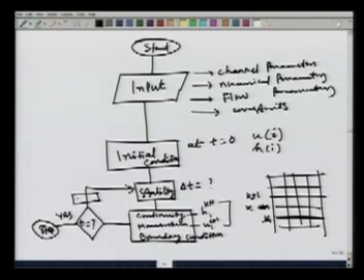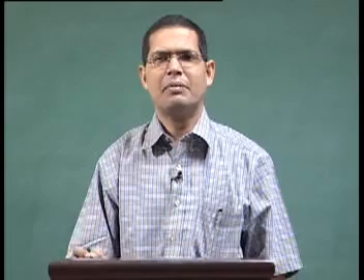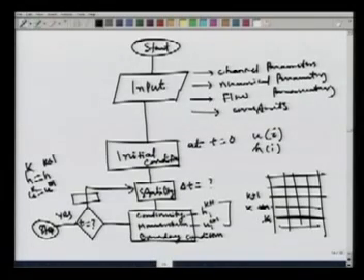So, here I should do h k is equal to h k plus 1 and u k is equal to u k plus 1. Then once again it becomes the same thing. That means now I am at time level k, which is known, and I move forward. But before going there, I should know what is stability, what is delta t. Then I solve the Lax diffusive scheme, put the boundary conditions and get the answers.